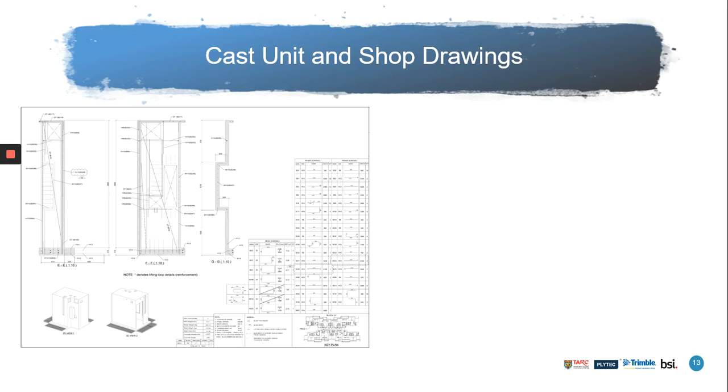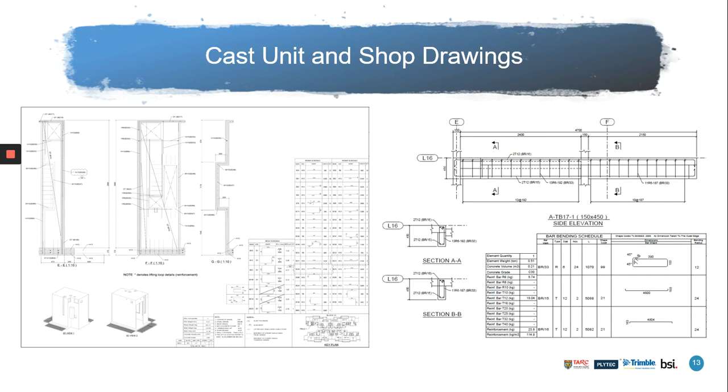So Tekla can cover the weaknesses in Revit, which in Revit they will not show you the bar bending schedule, but in Tekla you should be able to do that. And with that schedule generator, you can send it to the factory and they can use the factory to fabricate all the rebar, the shapes and sizes and length. So as you can see here, all the rebar are generated.